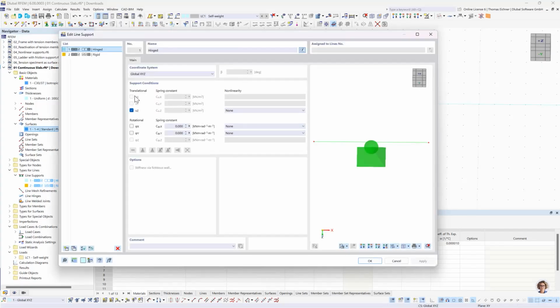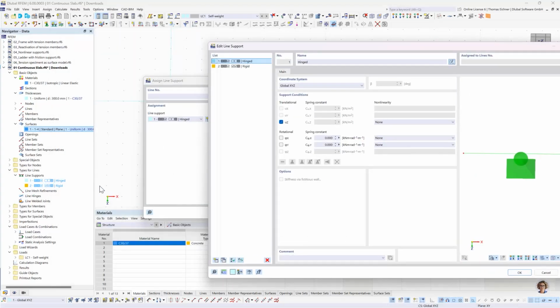And now we will see the benefit of our early decision to model it in the plate dimension and not in the 3D domain. That's quite simple. The program now helps us since we are in 2D plate. We don't need the deformations in the horizontal directions anymore. And we don't need the rotation about the Z-axis, which also would be a kind of deformation in horizontal direction.